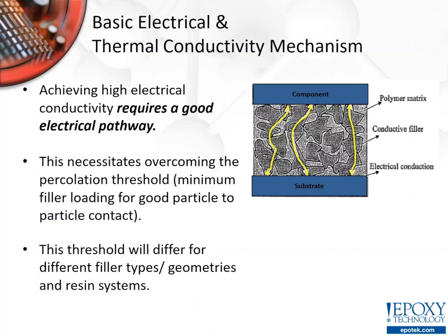Enough filler needs to be loaded into the system to overcome its percolation threshold. That's the minimum amount of filler that's required to get good interparticle contact. And that percolation threshold will vary with different materials and fillers that we add into our epoxy solutions.